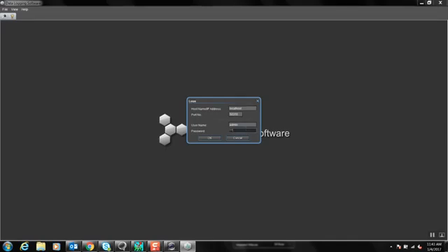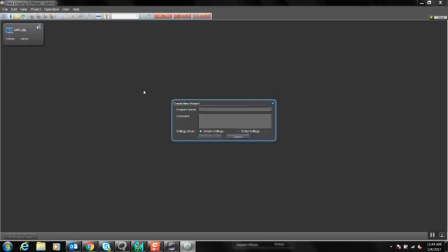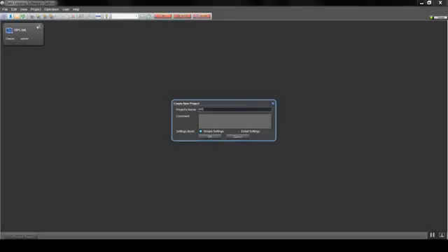Gate WT is now connected to the WT500 and is reading data from the power analyzer. Next up, we will set up the GA10 acquisition software. Since I've created an account before, I will log in. But if this is the first time using the software, leave all fields as default. We'll then go to File, New Project.